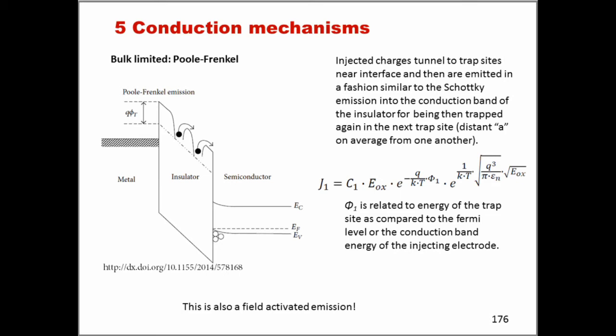Okay, and related in a way to the hopping mechanism is another very important bulk limited conduction mechanism that goes under the name of Poole-Frenkel. Effectively, the Poole-Frenkel mechanism is a combination of hopping and a Schottky emission. So as you can see, we can follow exactly the same example that we used previously. So same band diagram, same MOS device, but this time